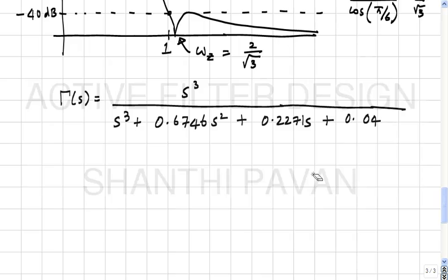If you keep truncating stuff right away, what will happen is that when you are going through the synthesis procedure, yesterday we saw that everything turned out nicely, right? So, you subtract this and then you take the residue and then things magically cancel and so on. The moment there is round off error, that cancellation will not happen properly, and eventually if you have a high order filter, suddenly you will start seeing negative inductances and negative capacitances coming out of the procedure, even though you have not committed any arithmetic goof. Okay.